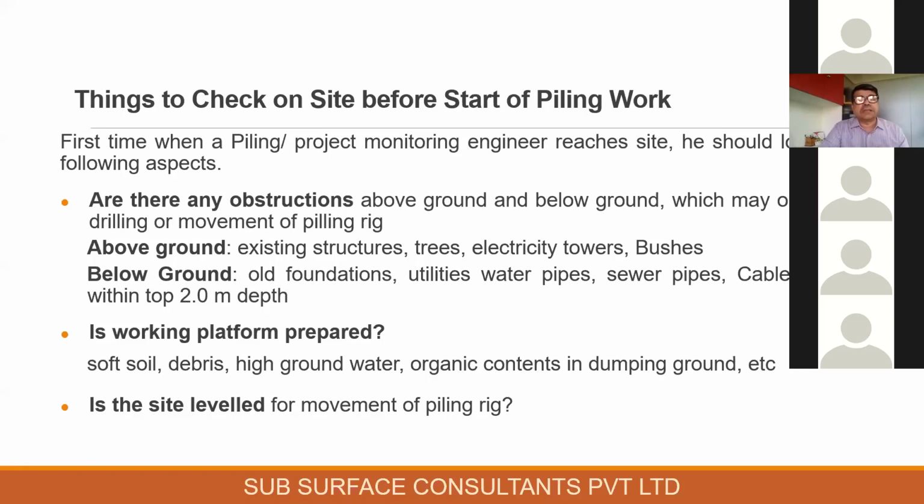Then the next is, supposing at site there is debris lying, or there is high groundwater, the soil will become soft. On such soft soil, it is not possible for a piling machine to travel very easily. There could be organic content in a dumping ground, like Deonar or, earlier, the dumping ground in the Malad area.